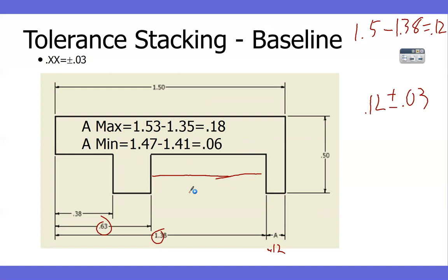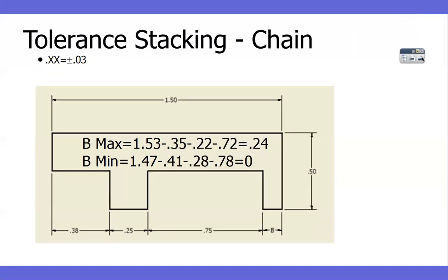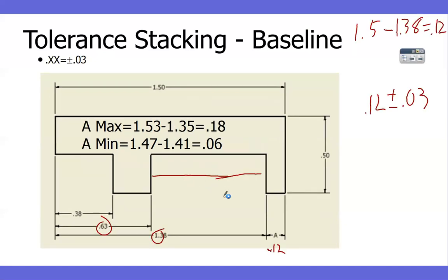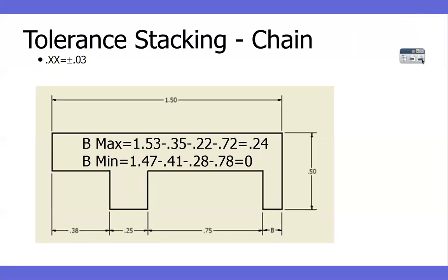So if I'm using 2 dimensions, what do I have to do? I have to have twice the tolerance. So same thing here. I have 0.06 tolerance, right? So it means that if I dimension it this way, it'll be 75 plus or minus 0.06. I go here. Now what's the tolerance on this section? Plus or minus 0.03. So the things I care about are dimensioned continuous between those two things that I care about. Does it have to be either this way or this way?